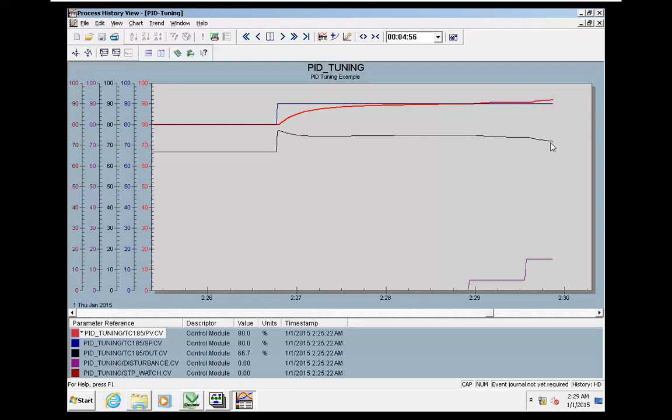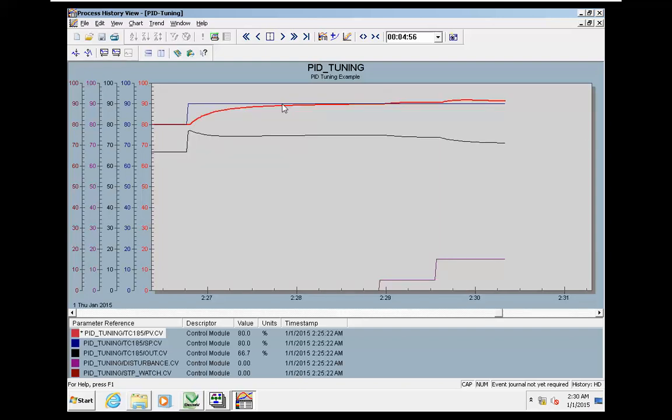The conservative PI parameters should be able to compensate the process and return to the set value. This is the second responsibility of the PID controller. The first responsibility is to regulate the process in order to reach the new set values. This part is okay. You can see that we reached the set value with a very slight overshoot.